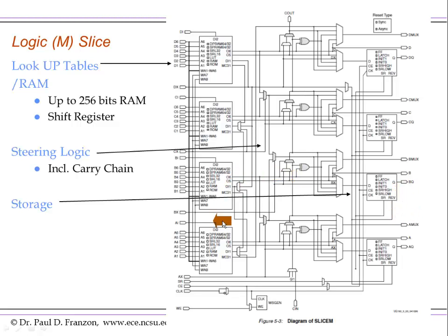There are scan chains that allow you to load in the bits into these SRAMs to build lookup tables or ROMs. In addition, there are storage bits not shown that control the configurations of these RAM blocks that actually specify for their specific design whether it's a RAM or whether it's a lookup table. This programming overhead is not shown here. In fact, the FPGA companies keep it quite proprietary so that you can't reverse engineer how to program their FPGAs.